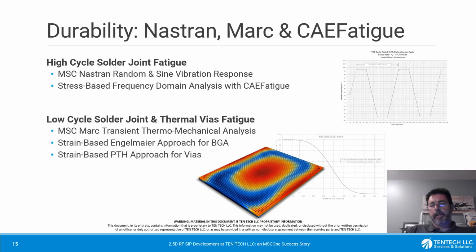This comes into play in our thermal cycles with the dwell time and the rate of change of temperature. So all this is built into our model. And for calculating fatigue, we use either custom subroutines or Excel post-processing tools to do the calculations.